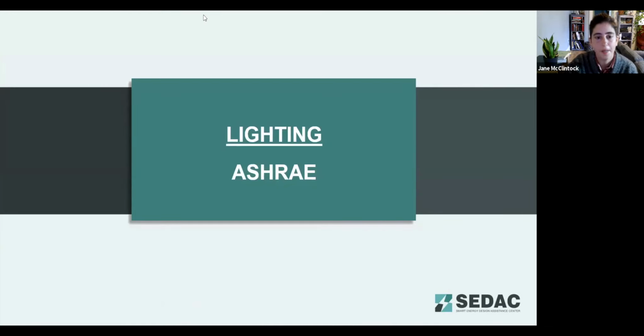So our poll: what categories need to be monitored under the 2019 ASHRAE? If you're using the current code, this may look like a tricky question, but remember, we're talking about the 2019. And then: where is automatic receptacle control required? The hint here is to think about what we're trying to control and what rooms would have the biggest opportunity.